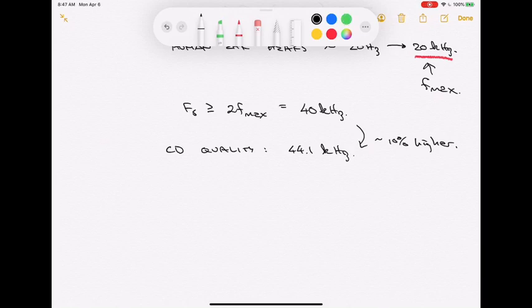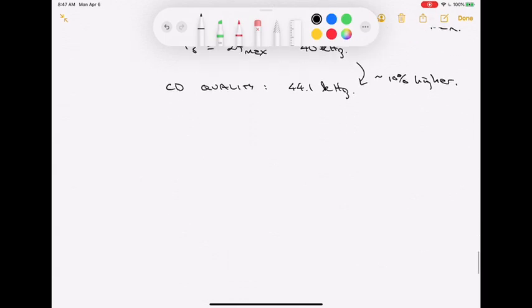We did a very simple example showing how this works with audio signals. Audio signals for humans go up to about 20 kilohertz, and so if we were going to represent that without aliasing, without getting those aliasing type errors where high frequency stuff sounds low, we would need to sample at least double that. CD quality audio ends up coming in at 44.1 kilosamples per second, or 44.1 kilohertz. Satisfies that Nyquist criteria nicely.